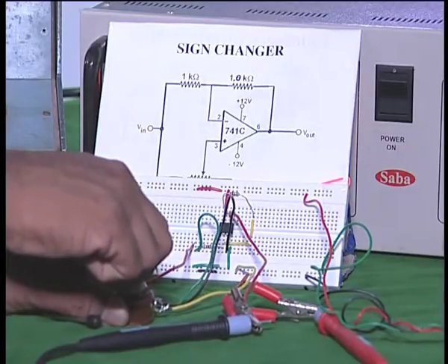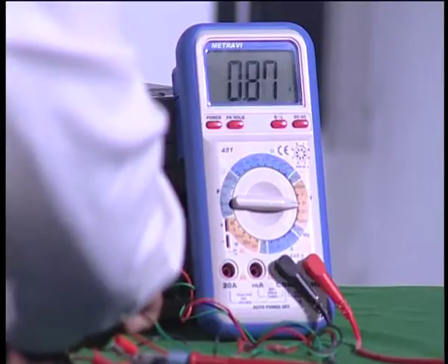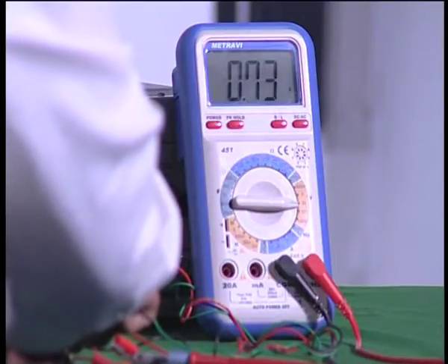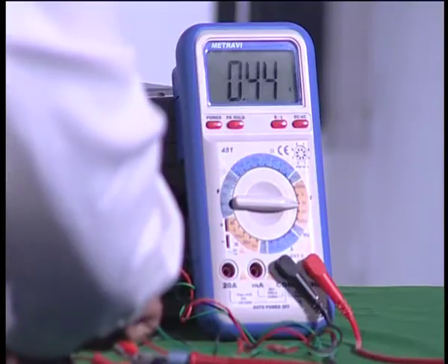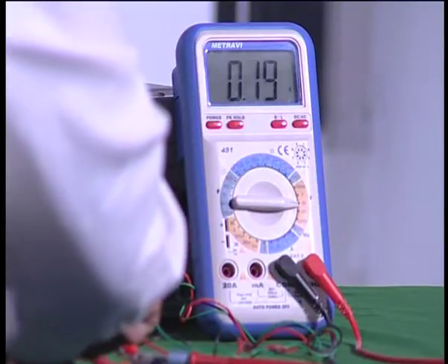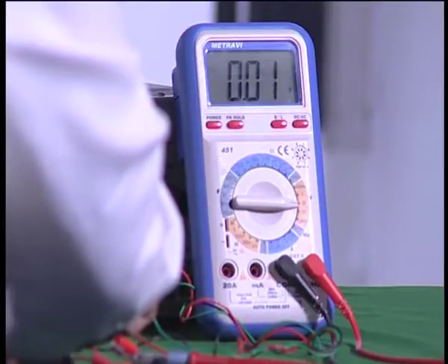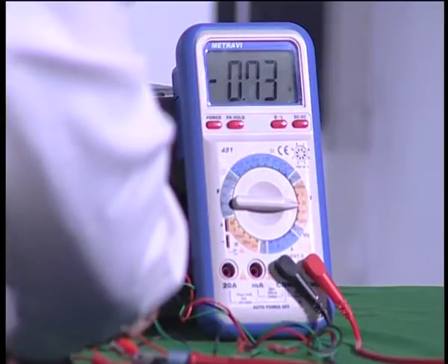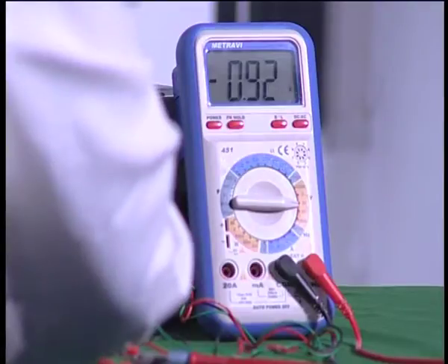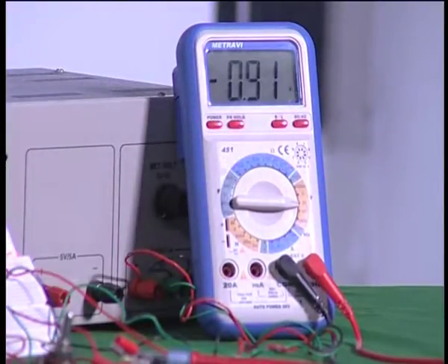You see the gain now starts coming down. As I increase the potentiometer, the gain keeps coming down, the output voltage keeps coming down, and then I almost come to 0. Then as I keep increasing, the gain starts increasing on the negative side, -0.3, 0.4, 0.5, 0.6, 0.7, and so on. When I go to the maximum, it comes again to nearly 1 volt, minus 0.91, which is closely minus 1 volt. Therefore, I have changed the gain continuously from plus 1 to minus 1 by changing the potentiometer from a 0 value to a maximum value.